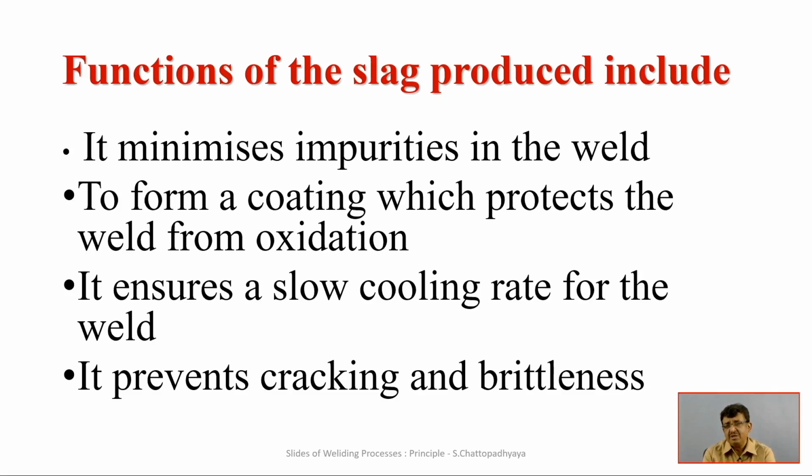It will form a perfect jacket which protects the weld from oxidation, and that is crucial because oxidation will jeopardize the strength of the weld. That was not known before World War I, and that is why welding application was very limited and it was only for academics. But when people knew that oxidation can be prevented, and then a high quality weld will be there, welding became the process of joining, with tremendous application during World War II and the post World War II period.